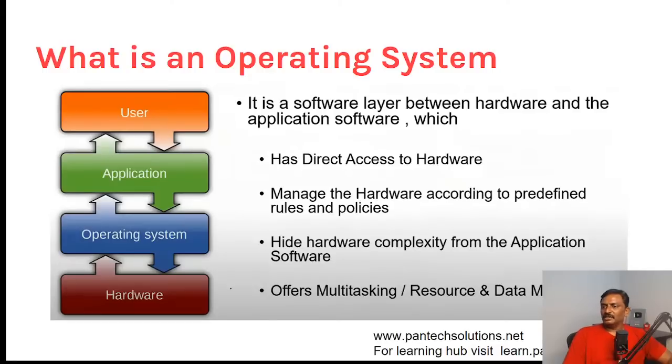The logic analyzer is used to get the logic, whether it is high or low. Especially, the logic analyzer is widely used for FPGAs. When you have multiple GPIOs sending signals, you analyze the waveforms, such as PWM waveforms, to see whether you are getting the right on time and off time. So the logic analyzer plays a major role.